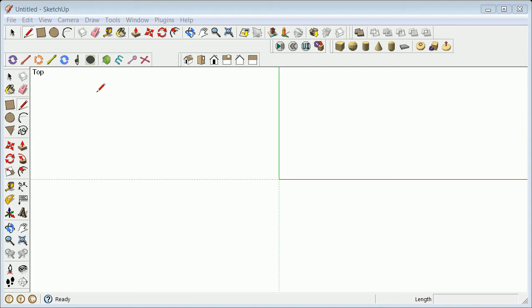The reason we're talking around that fact is that many of you have AutoCAD training in 2D, and that is great and perfectly transferable over to SketchUp or over to Inventor by making sure that you make things in blocks. So you're better off making your blocks within AutoCAD, either a lot of blocks within one drawing or separate drawings, by doing a block command and then a WBLOCK command.